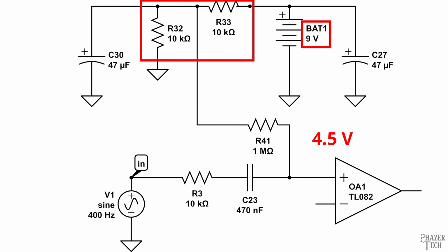But what happens if you wanted to connect that pedal to another pedal that's running at a different voltage, or an amplifier that runs directly off AC voltage? The reference voltage of our pedal would be a problem when connecting it to these other devices, which is where the coupling capacitor comes in.